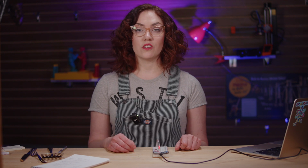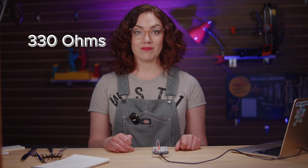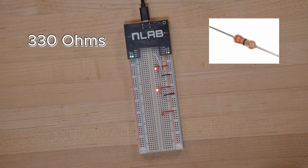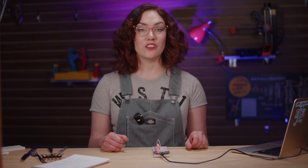In order to increase the brightness by 10, we can reduce the resistance by 10. So instead of 3,300 ohms, we'll use 330 ohms. That's orange, orange, brown. Whoa! That is way brighter. But keep in mind, because it's 10 times brighter, it's actually using 10 times more current from the battery.